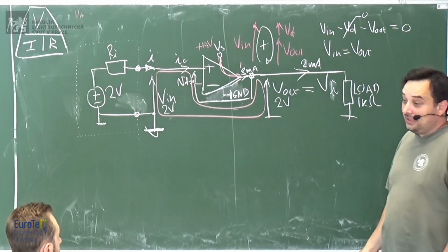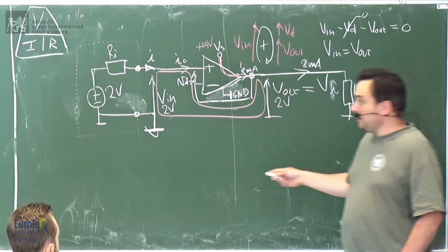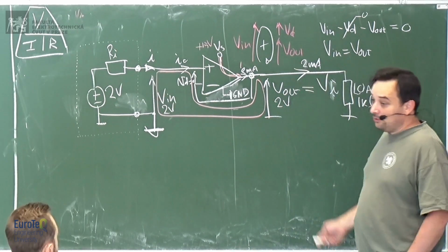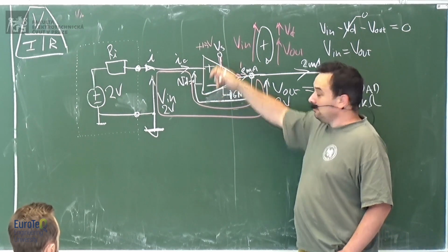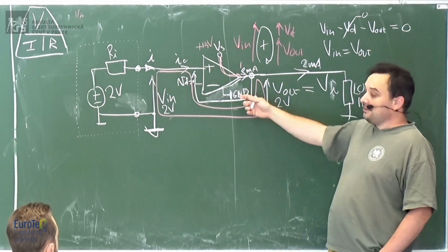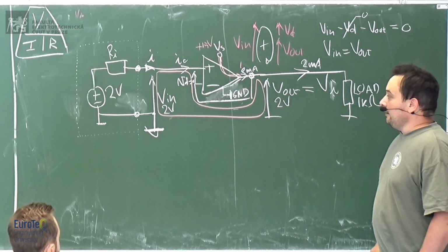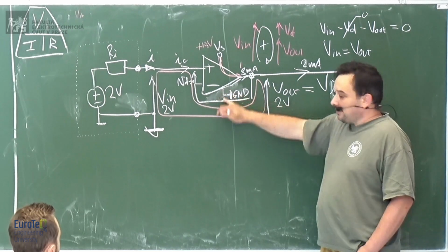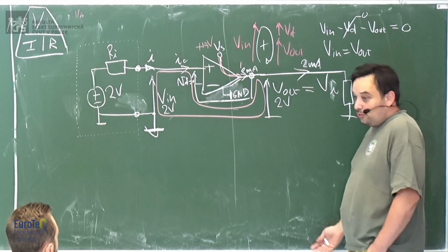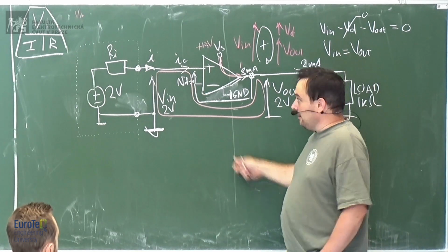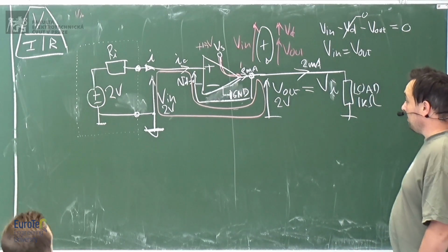But you must know that then you can only have positive voltage here. You know that it will be from the input from ground to plus 15 volts, actually ground, a little bit, almost ground, not real ground. So technically there is nothing preventing you from connecting it to ground, as long as you know that it will limit the range that you can operate it.